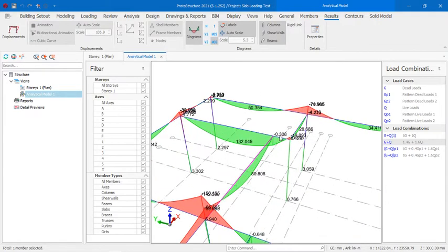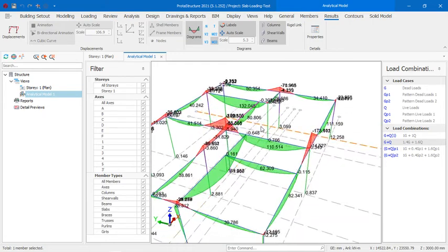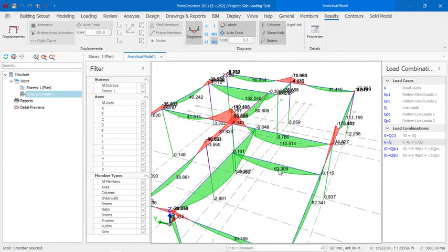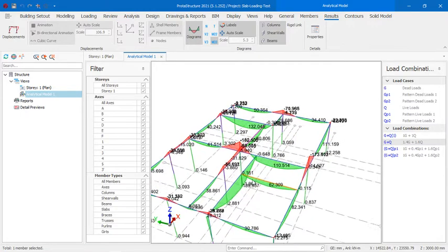So we can see that the software does not take care of point load where you don't have columns and you have a beam that is acting as support for another beam. So this will be your secondary beam, this will be our primary beam, and this will be our secondary beam in this case.